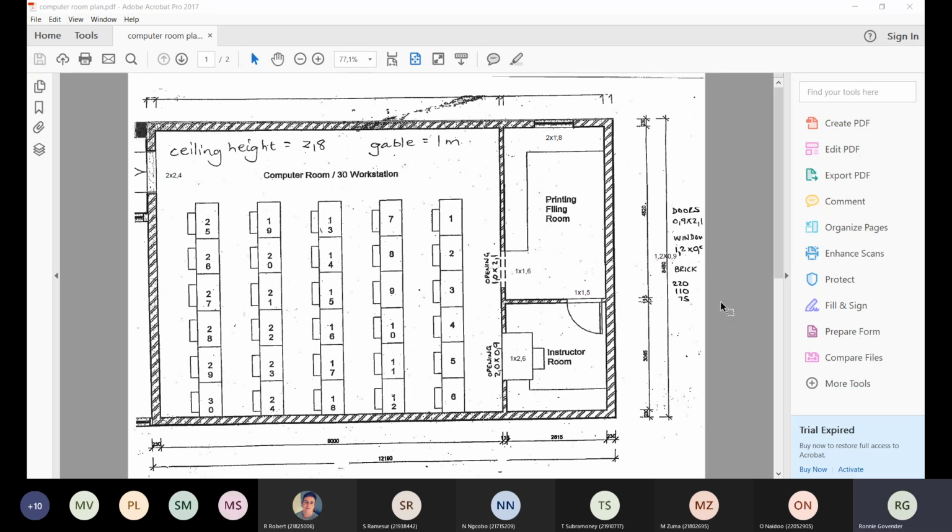Yes, sir. Yes. Thank you. Right, perfect. Similarly here, if you look at this door opening here, it is 1 meter. So 1 meter plus 300, I'm going to need a 1.6. Same here, this is a 2 meter opening. 2 meters plus the 300 gives me 2.6. But because the internal walls only need one, I don't have to place them side by side. And that door there was 0.9 plus 300, which gave me 1.5 meters. Those are all the lintels that I'm going to need, right? Those are the lintels there.